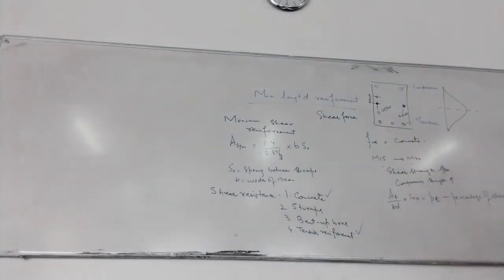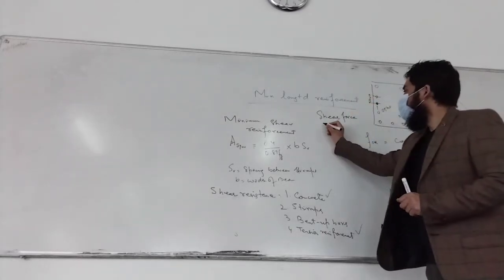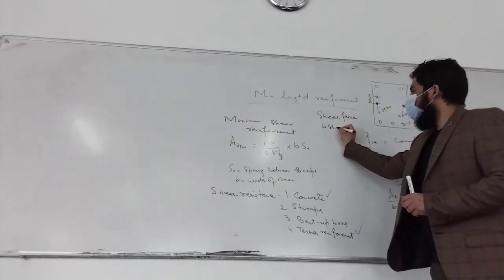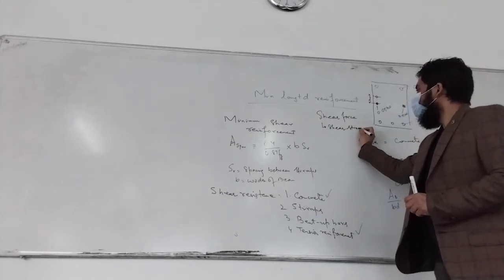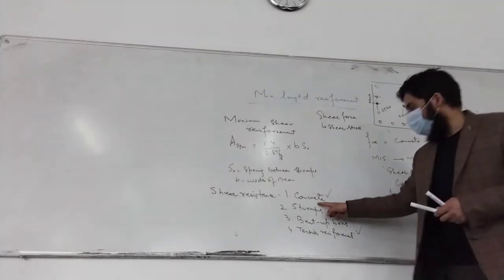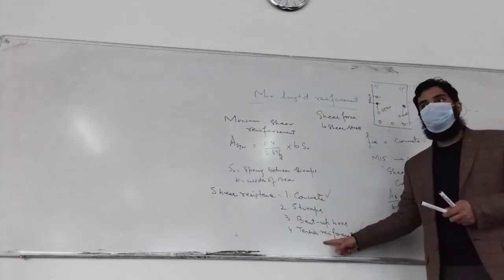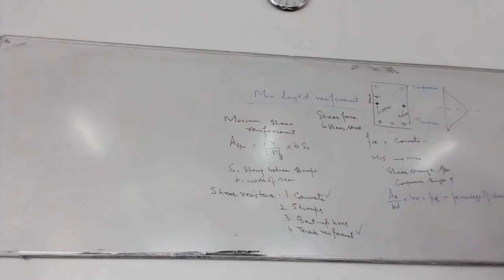पता है ना how we calculate for a beam? बनाया है ना आपने, how to analyze. Shear force से आपको क्या पता चल जाएगा? Shear stress कितना उस बीम पे आ रहा है. अगर ये shear stress जो उस बीम पे आ रहा है, if it's greater than the design shear stress from concrete and tension reinforcement, जो कि इसमें दिया हुआ है tau c, ये table 19.